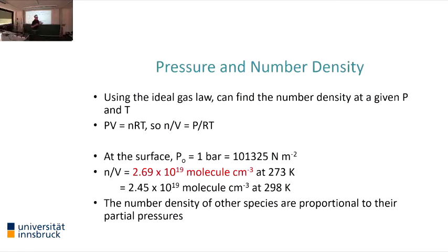Typically for indoor air quality, there is not a good marker to monitor virus load, for example, but CO2 is a very good marker. We are all in here exhaling CO2, and there are some empirically determined thresholds: when CO2 concentrations go way beyond 1,000 ppm, it's time to open the windows. For many reasons, but this year, of course, that's also one measure. They are propagating more and more now to monitor indoor air quality in the context of the situation we are in.